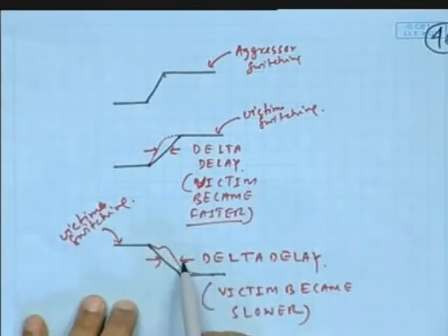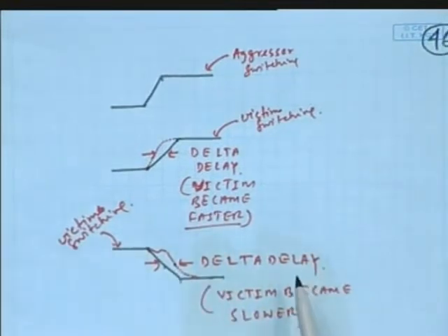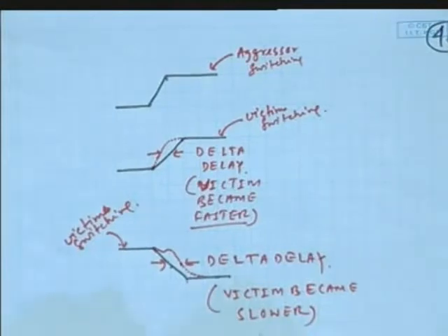So delta delay will be introduced. See where the effective transition can happen, it's at 50% say. So from here to here it has switched, right? That's the delta delay you are calculating when you are doing the crosstalk analysis. So the victim becomes slower here. Clear?